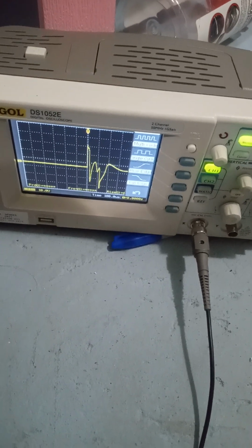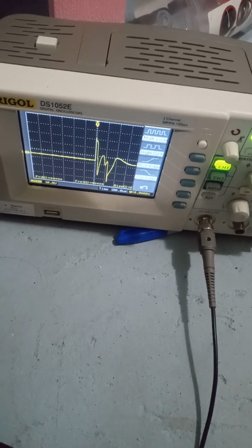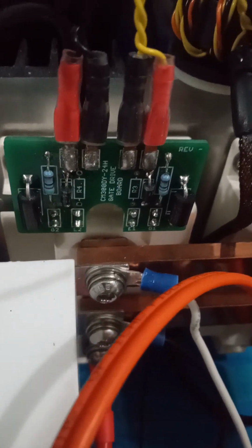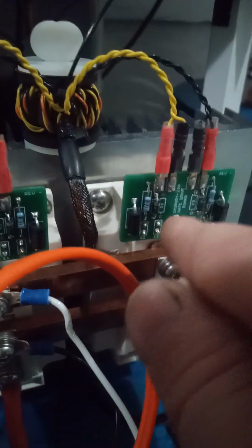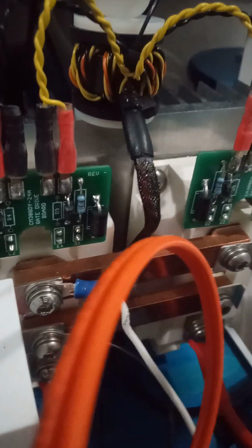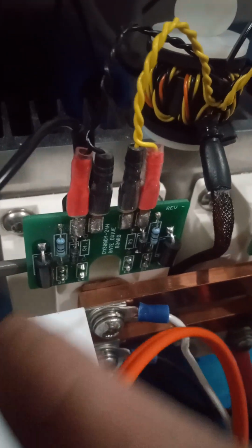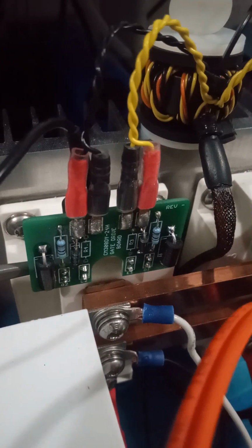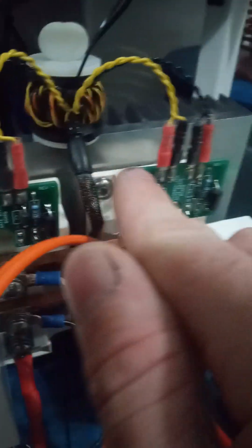Then you can hear it, and there's your on function right there. So gate 1, emitter 1 of IGBT1, or actually it's gate 2, emitter 2. It doesn't really matter on the labeling as long as you go across from left to right. So the first set of gates, that's how we're going to label it. That's switching on. So as we said, we want the bridge to switch on. So on, off, off, on.